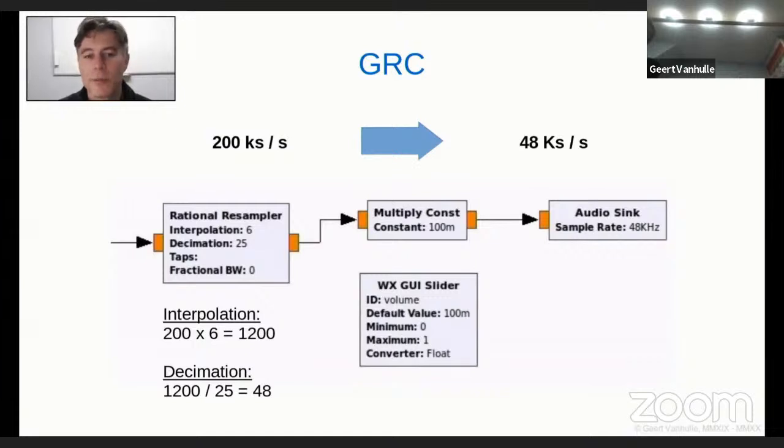And it's not interesting. The information isn't really valuable anyway. So this is the second reason why we will reduce the sample rate downwards as well. So two reasons in this case. One, to adapt to the physical sample rate of the hardware. The second one, again, to reduce the processing required for processing the samples.